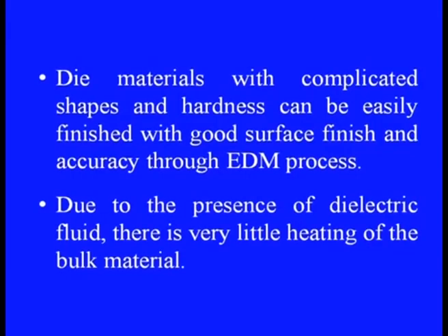No physical contact between the tool and the workpiece, and therefore the associated forces are not there. Die materials with complicated shapes and hardness can be easily machined with reasonable surface finish and accuracy through this process. Due to the presence of dielectric fluid, there is very little heating of the bulk material.